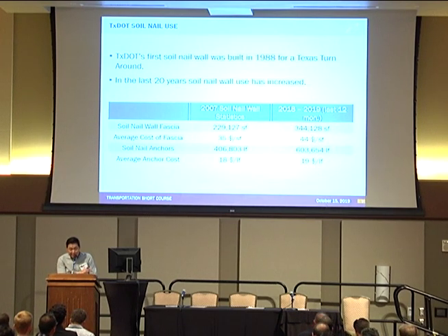As you can see in the table, the soil nail retaining wall is typically paid under two items: Item 423, which is the soil nail retaining wall fascia, and Item 410 for the soil nail anchor, or Item 411, which is the rock nail anchor as well.